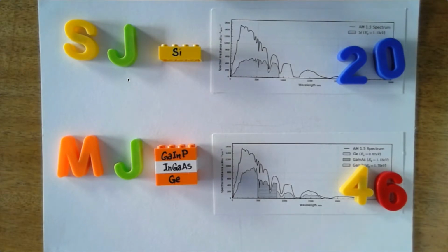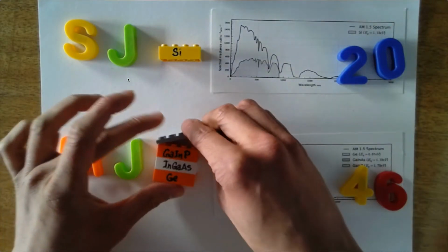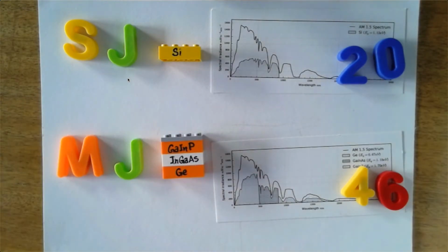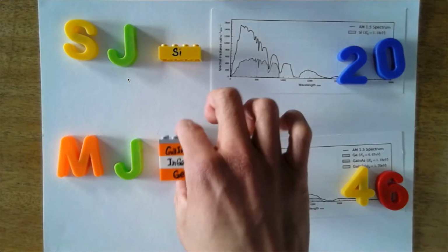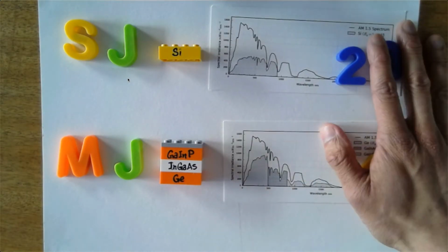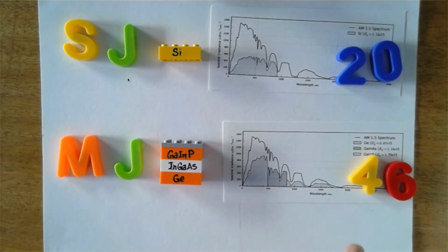And to achieve such high efficiency in a commercially viable and economical way, these multi-junction cells are typically topped with an optical concentrator, which is represented by that. So that means that unlike a typical silicon single junction cell, which can absorb diffuse solar radiation from all directions, these multi-junction cells topped with a concentrated system can only accept photons from a very specific direction. And that has implications, as we see later, to how we actually count up the number of photons that these devices can actually see. Okay, so the bottom line is that multi-junction cells, as you can see, have more complex,